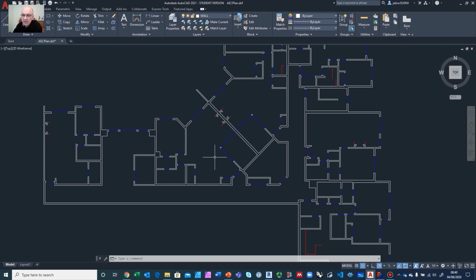The other thing I did is I found some overlapping lines, and this drawing was not clean. So you find these edges that look as if they're one edge, but they are made out of multiple edges on top of each other. Topologic should be able to handle this, and it handles it in most cases, but sometimes, because of tolerances and floating point decimal points, it can miss some of those. So just not to get into trouble with that, I went ahead and cleaned all of that.